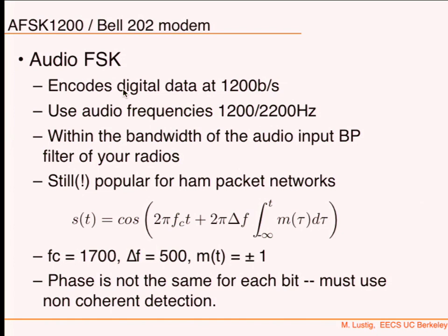The nice thing about AFSK is that it is not baseband. So you don't switch frequency about a baseband. You switch between frequencies that are audio tones, and they're going to be FM modulated afterwards. Don't forget that. It's not that we're putting a DC bias on the radio that will switch its frequencies. That would be one way of doing things: putting a DC bias on the radio, then it will switch between two frequencies in the RF. But that's not what's happening here.